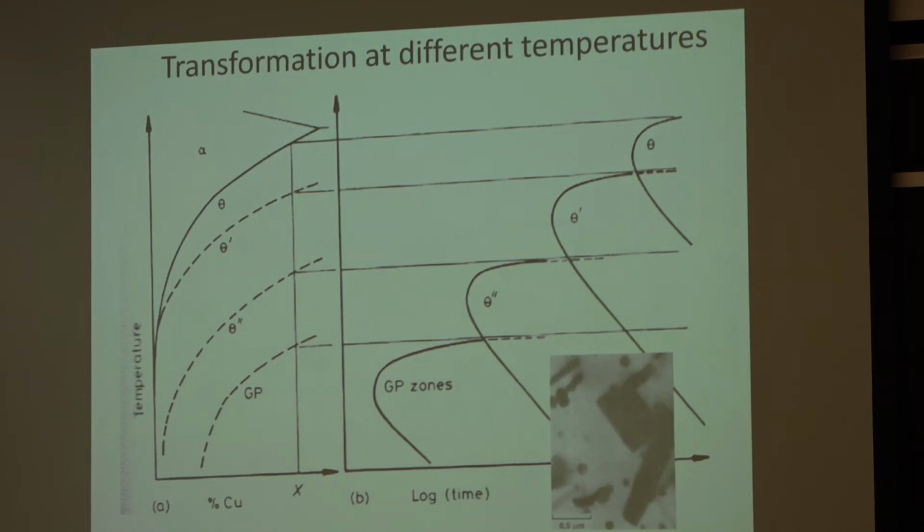So there's a process here with aluminum where you have to take it from hot, and when you quench it, all you do is prevent all these transformations of making precipitates from taking place. You just completely avoid the diffusion process, and then you heat it up again. And that's what we call the aging. So when you have a 6061 T6, it was solution treated to a single phase, quenched to freeze that microstructure. Now that quench condition is not hard. It's essentially soft. And then you go and reheat again to increase the strength by forming precipitates.